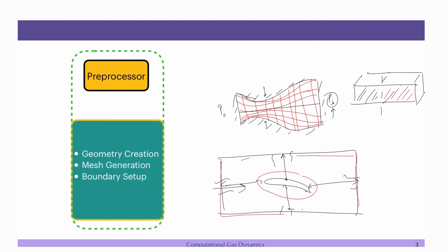If you have a periodic boundary, let us say you are doing flow over a turbine that we have been discussing, then you have one turbine on the top and one turbine at the bottom. So, what is the distance between these two? This should be the periodic boundaries, this one and this one, and so on and so forth. And then you have inlet and outlet. So, all the boundary conditions that you have studied will basically come into play here.